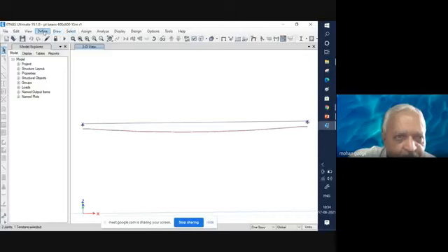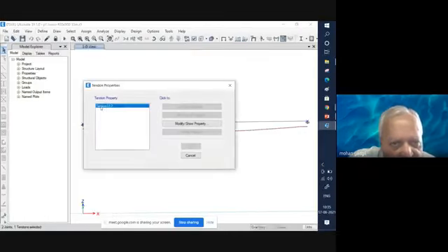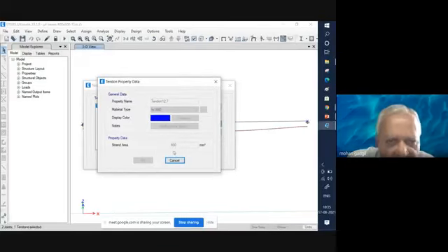As far as the definition of the cable is concerned, you need to consider over here this tendon section. Now this tendon section you have to define. So I have considered this tendon of 12.7 mm diameter, and I have considered for this the strand area as 600 mm square. Now if you see this 12.7 single strand, its area is approximately equal to 100 square millimeter. To be exact, it is about 98 point something, but we will take it as 100. I have taken 6 strands per cable, and I have taken 2 such cables. In that case, what area I am providing is 2 into 600.